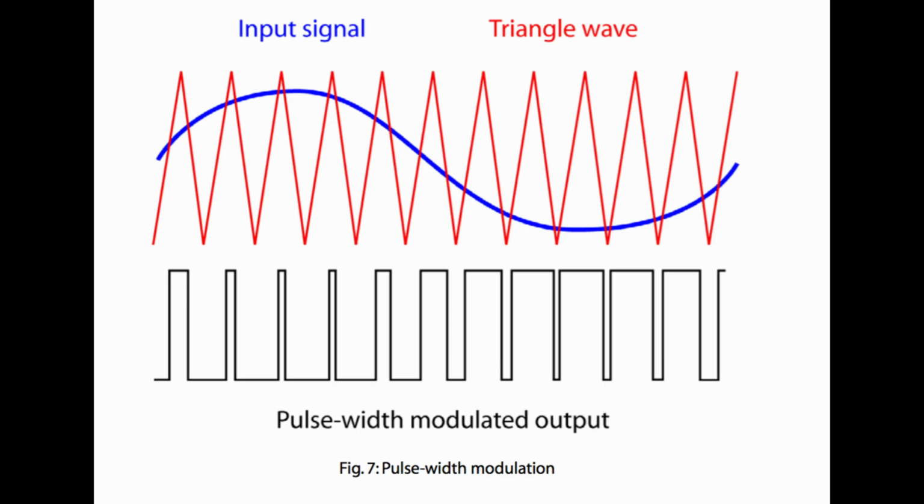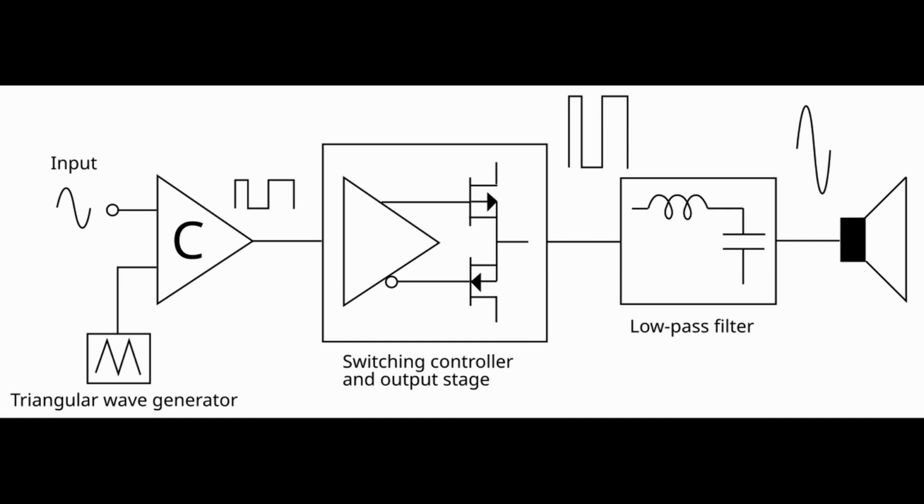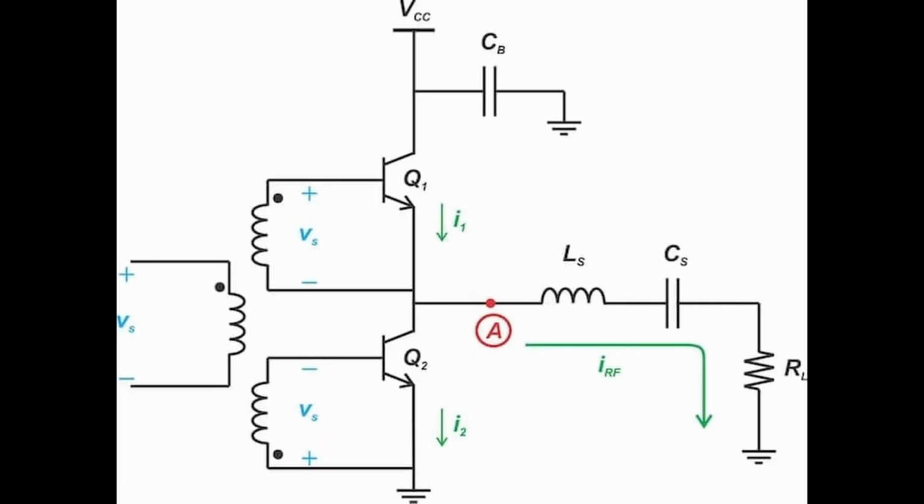Wow, so GaN just gets rid of that problem. Pretty much. By removing that QRR issue, GaN basically gave designers the freedom to crank up the switching frequency, get that high-fidelity audio resolution, without the huge penalty in noise and heat loss they used to pay with silicon. That's a game changer. A new material just bypasses a fundamental limitation.